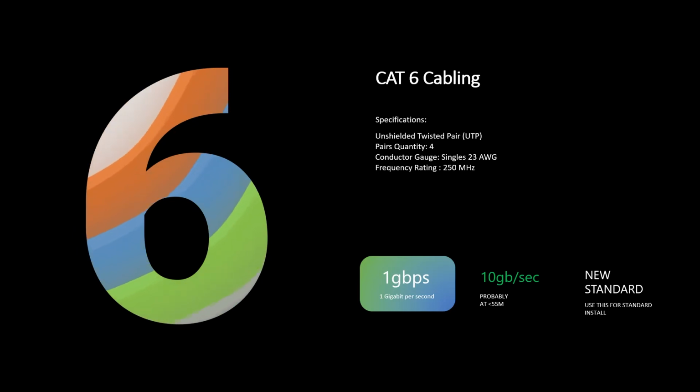So the more shielding you put on something, the better it's going to perform in that regard. It's just a question of how much needs to be there in order to meet a certain specification. And there are ways to reduce crosstalk without putting an actual shielding system on it that has ground wires and all the complication. So Cat 6 and Cat 6A have this vague range between each other where, so long as you're not going for the Cat 6A that's shielded, it all blends together a little bit.